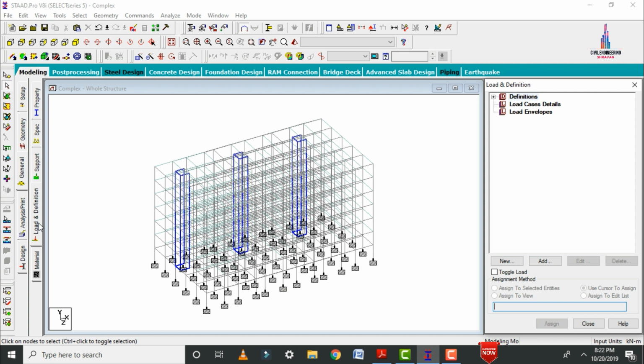So for this respective building, I am assuming the load cases will be consisting of only the gravity loads only. So why? Because this building was located in zone 2 condition due to the effect of the less amount of the seismic zone factor in zone 2 condition. I am considering it as zone 2 condition. Okay, so in zone 2 condition basically we will eliminate the seismic loading condition. So for that reason only I am skipping the respective value of seismic loading condition.